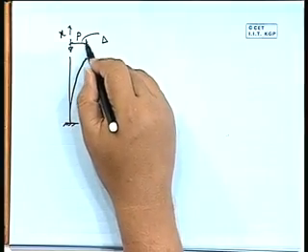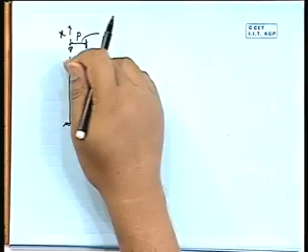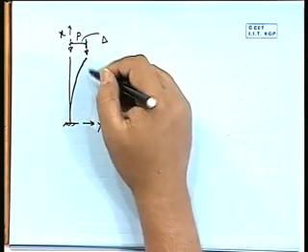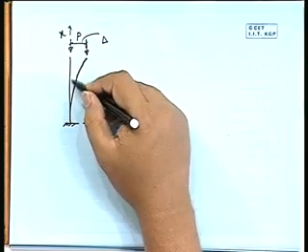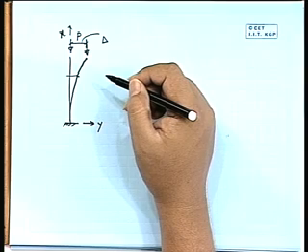So delta is the tip deflection and it will follow a cantilever mode of deformation. Now we have x and y, so at any point there will be a bending moment. Now P will be shifted from here to here. Initially it was straight, the load was here, now the shape is different, the load is there. So at any station, from x, what will be the moment?